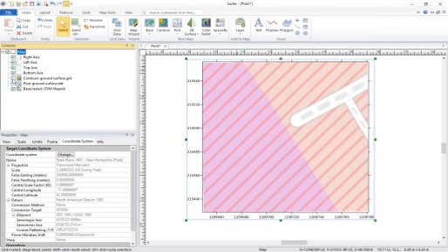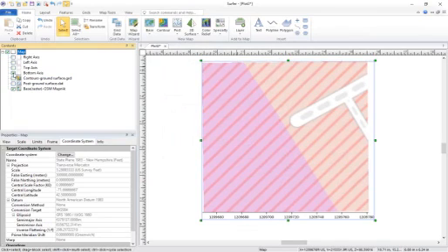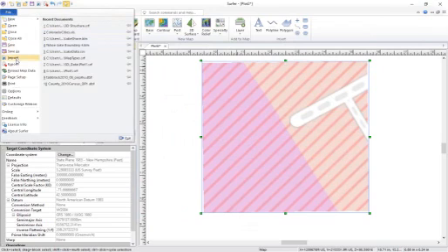But before we move on to assembling the model in Voxler, this image needs to be exported from Surfer. So in the contents window, I'm going to click off the visibility checkboxes for the axes, and make sure the contours and the post layers are also checked off, as I don't want those in the resulting export. And then I can click File Export.